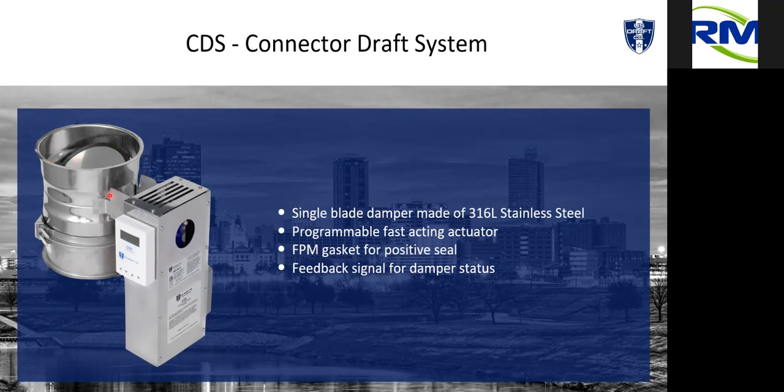Again, that same actuator we talked about with our multi-blade damper is now on our CDS, so it's 2 seconds full open to full closed. Controller, all pre-programmed, can be set anywhere from -0.5 to +0.5, so a lot of flexibility for your appliance setup there. And this is exactly how it comes from the factory. All they have to do is bring power, call for heat, feedback to the boiler, and they're done.